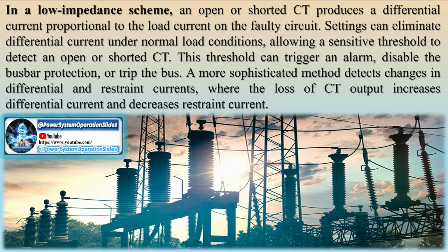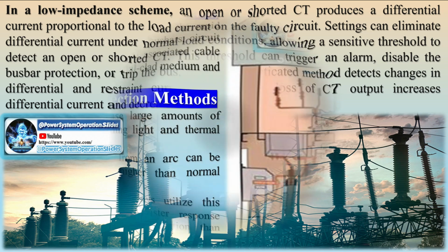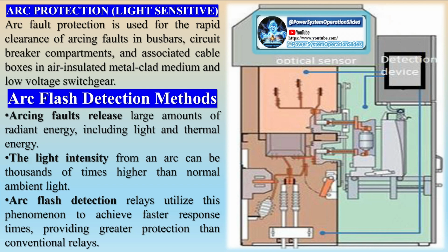These relays minimize tripping time and limit damage from high fault currents. Modern systems often use double busbar protections. Design considerations: key issues are reliability, operability, maintainability, and cost. High reliability solutions are justified at EHV-HV levels. Busbar protection systems should dynamically replicate bus topology and offer design flexibility to protect all bus arrangements.